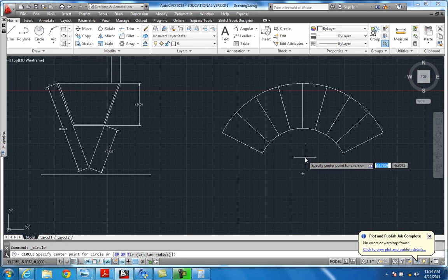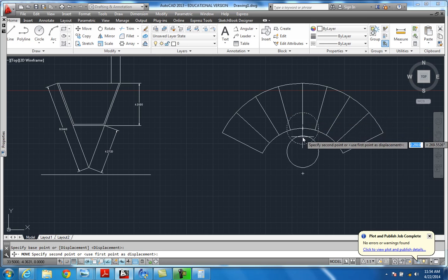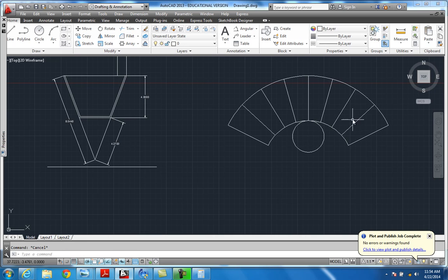radius, and I'd put it right in the center of it, and we'll move it. This is actually going to be a radius of 1.5, enter. Just hit move, grab that object and bring it down to the center. Now when you print this out, it looks like a coffee cup. This right here will be the outer part. This will all enclose on top of this circle.